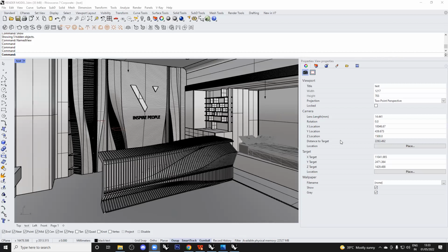And what is the difference between Dynamo and Grasshopper? The difference is that Dynamo is the same as Grasshopper, but for Revit. But it's fairly new, because Grasshopper was starting to become really powerful when compared to Revit modeling. So they wanted to incorporate a parametric engine as well, which is why Dynamo was introduced. But it's fairly new, which means the resources available for Dynamo are very limited. Grasshopper has thousands of plugins, whereas Dynamo will hardly have hundreds of plugins. So for the resources you need to come up with any kind of models, I would say Grasshopper is much more superior. I personally prefer that.